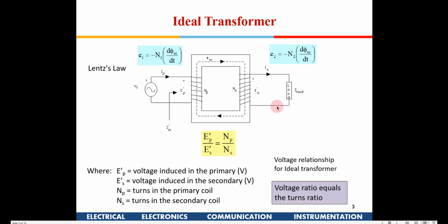These kinds of small transformers, you will find in your mobile chargers and laptop chargers, where you have a 230 volt supply. You require a DC voltage of only 5 volt or 6 volt. So the very first thing we need to do is bring down that 230 volt to around 10 volt AC, and then rectify it into a DC voltage. These are known as step down transformers, which you will find in most of your mobile and laptop chargers.